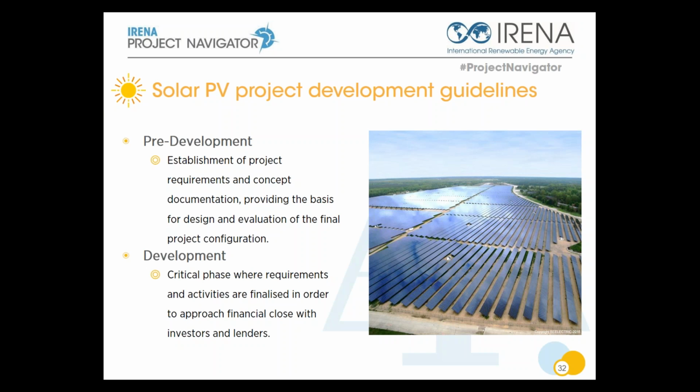Also, we look at thermal degradation because, of course, we're looking at projects, as Mr. Gillen explained, in different locations. So, for example, if you have a cell temperature of 60 degrees, which can happen in desert areas, the actual power output compared to the traditional standard 25 degrees Celsius will be 16% lower. So essentially, if you didn't take into account thermal behavior when estimating the performance of your project, the technical engineers from the banks will degrade your power output by more than 16%. So very important that we provide this.